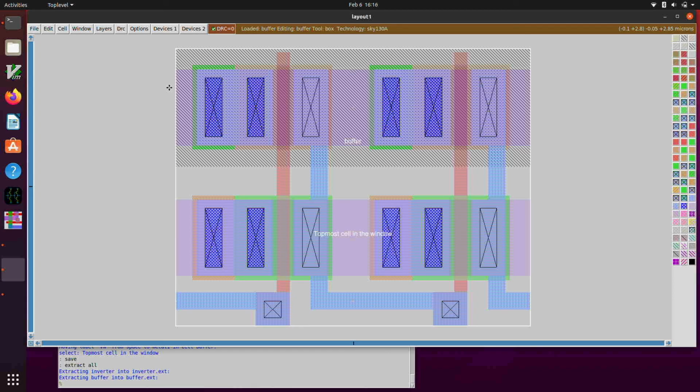Okay, but there are a couple of settings we have to change. The first is we want to make it a hierarchical netlist, and so we're going to do :X to SPICE hierarchy on, and we want to do X to SPICE scale off. That has to do with the physical dimensions of the widths and lengths of the transistors and how they're written out to the SPICE netlist.